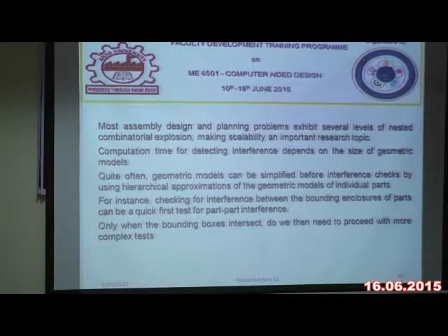Computation time for detecting interference depends on the size of the geometric models, that is, the execution time. Quite often, geometric models can be simplified before interference checks, as an improvement of the solid models according to automated design for manufacturing. Checks can be made using hierarchical approaches, which we have already seen. The hierarchical approach is a combination of the feature based and the homogeneous matrix based.